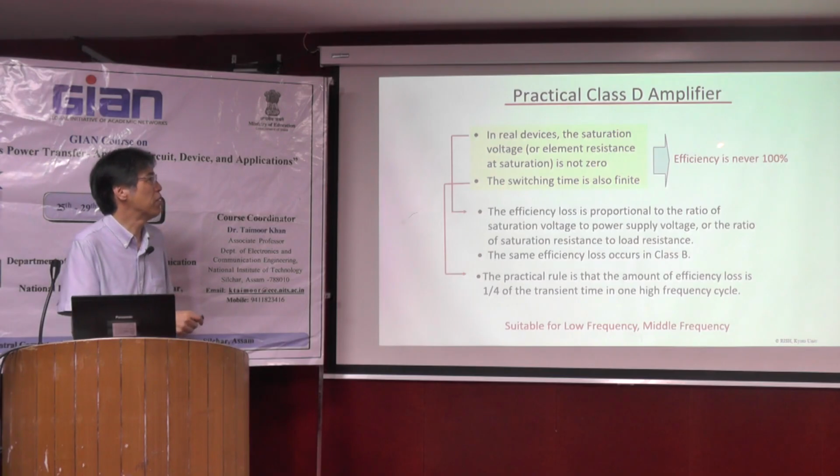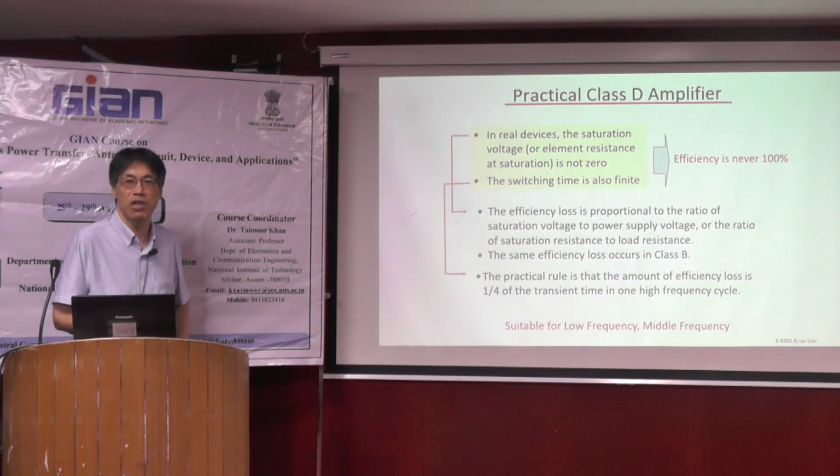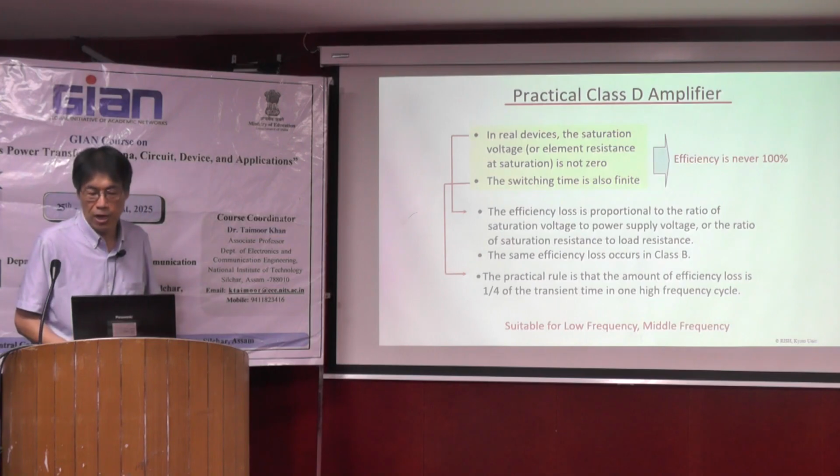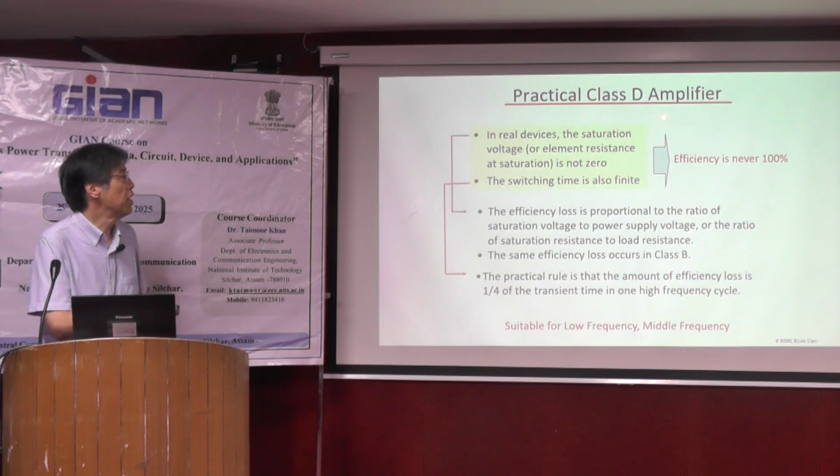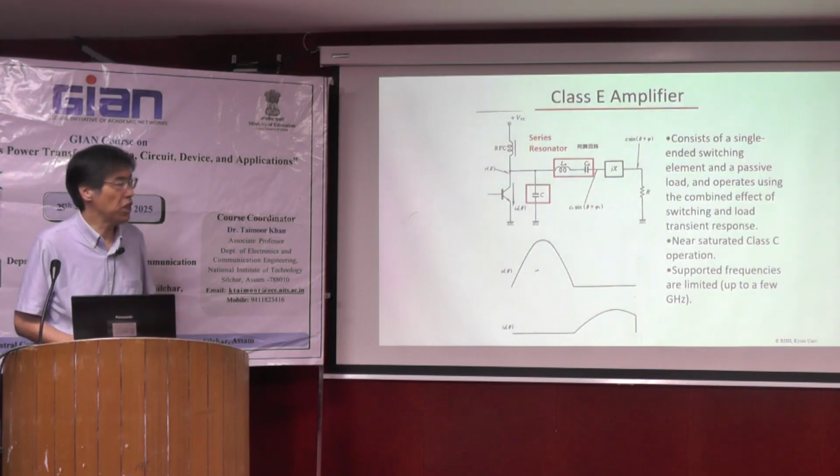So in reality, efficiency is never 100%, and this saturation voltage is a frequency problem. Usually, this class D is not applied at microwave frequency. Usually, you find papers on class D in lower frequency applications, sometimes inductive WPT or etc.